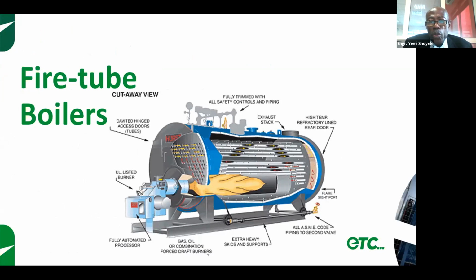And the picture that you're seeing shows exactly what happens. This is a 3-pass boiler. That is, the flame is established in the furnace, which is considered to be the first pass. And then the hot gases make 2 different passes. The first one is a reversal after the back plate to the left. And the third pass is on the way out towards the right. And then the exhaust gas goes out of the stack. Okay, this is fairly common in manufacturing industries.